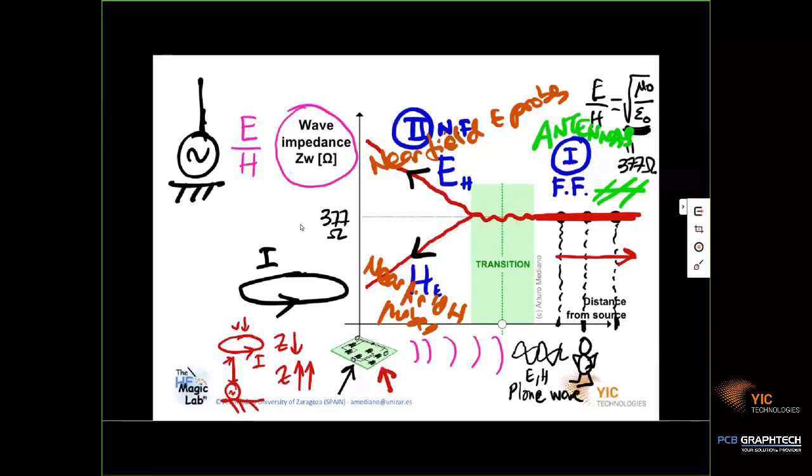If you go to electromagnetic theory, this is a known, very easy task to calculate. But in EMI debugging, we consider that the distance where we can go from the near to the far field is basically lambda over 6. So you need to calculate the lambda, the size of your signal, to know the distance between the near and the far field.